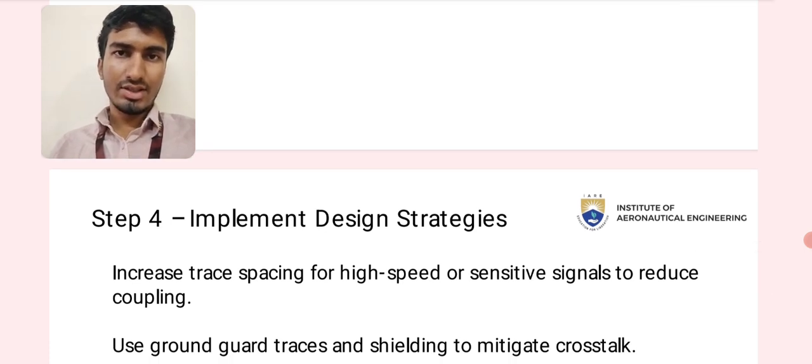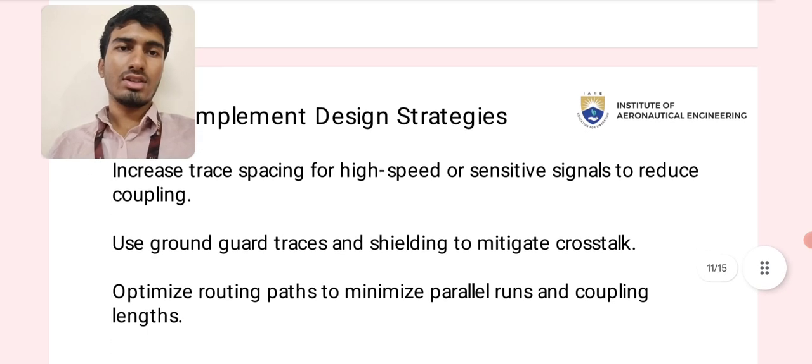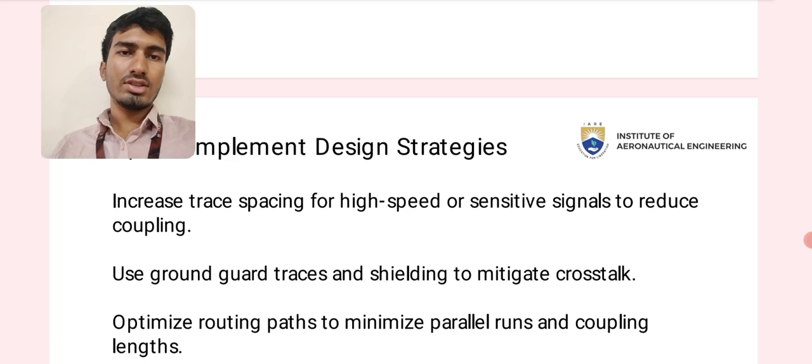Implement design strategies. Increase trace spacing for high speed or sensitive signals to reduce coupling.